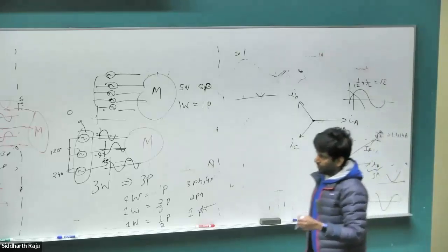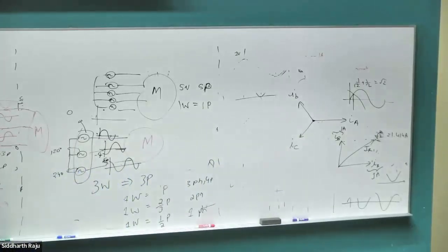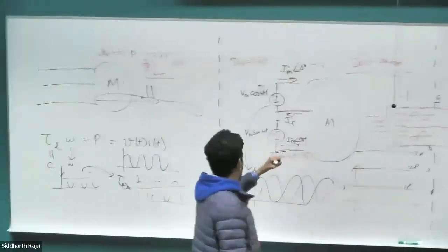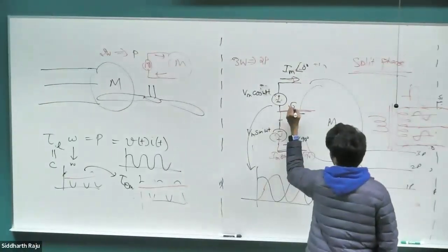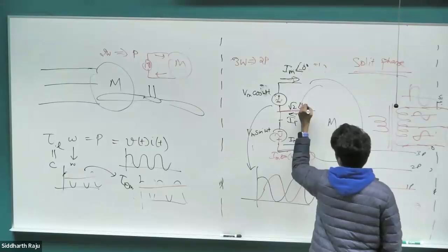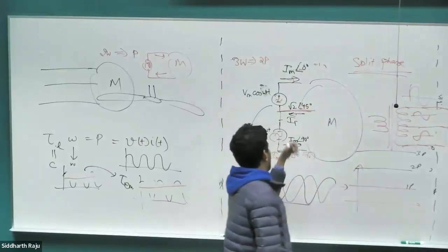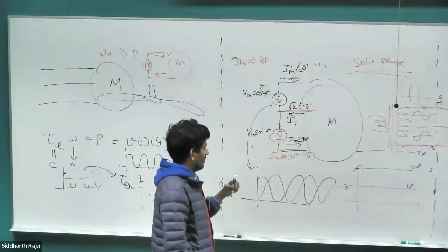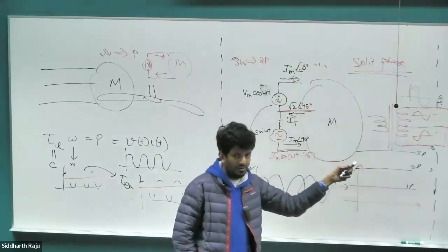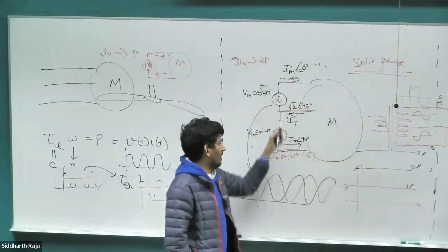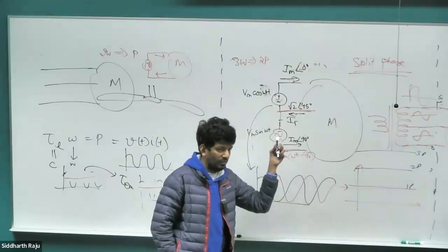So this is the other big problem with the two-phase system. Not only is the power limited, but the third wire carries more current than the other two wires. At some angle, 45 degrees. Right, the angle itself is irrelevant. But in a three-phase system, all the wires carry the same current. In a two-phase system, two wires carry one amount of current. The third wire needs to be rated in a different way.